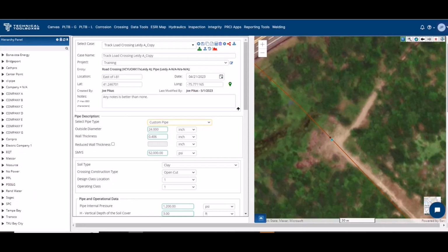The overburden is considered soil-only load. As the evaluation effort was undertaken, the first estimate of soil load on a pipe was that of the pipe supported by the entire weight of the overburden. Well, that's pretty conservative. So Spangler developed a load coefficient that predicted how much the overburden is carried by the pipe. This load coefficient is a function of the burial depth, which is part of the parameters that we input, trench width, and a friction coefficient between the backfill soil and the pipe trench walls. And that's a default in the calculations.